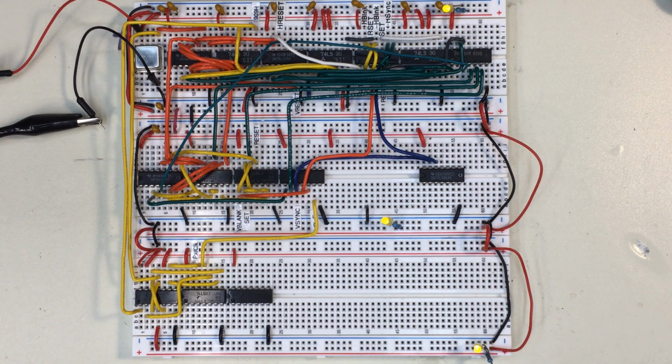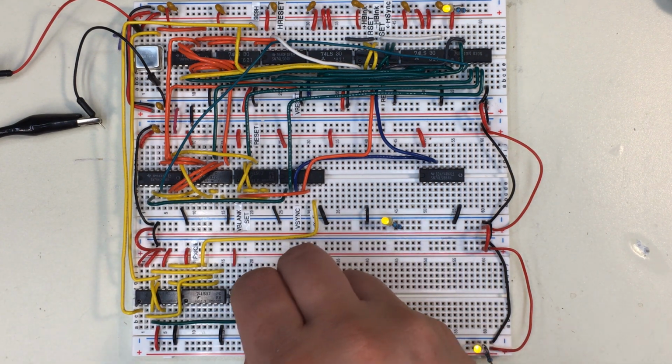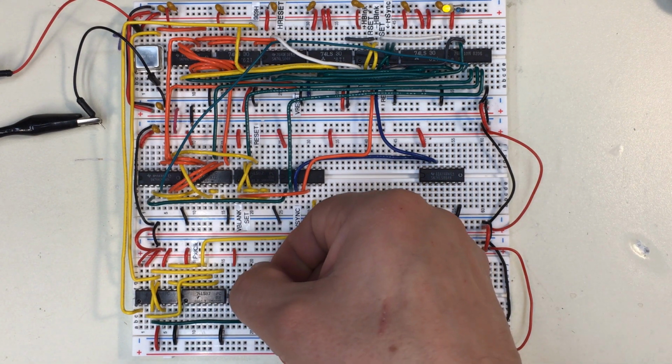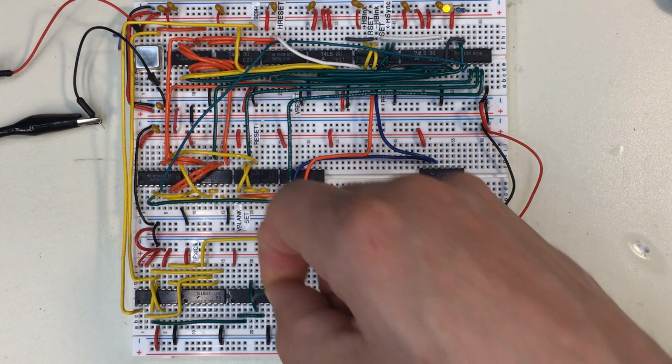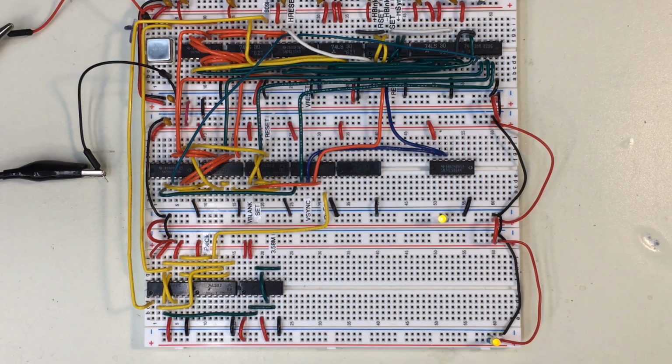So let's build it. First, we bring the 14 MHz clock into the clock line of the first flip-flop. Then we connect 1D to 1 not Q. Next, we connect 1Q to 2 clock. Then we hook 2D to 2 not Q. I forgot to show pull-ups on the clear and preset lines. Don't forget those. And the 2Q output is our 3.58 MHz reference signal.